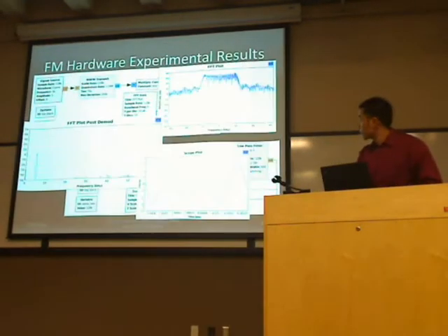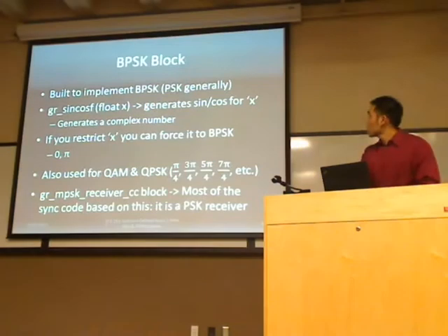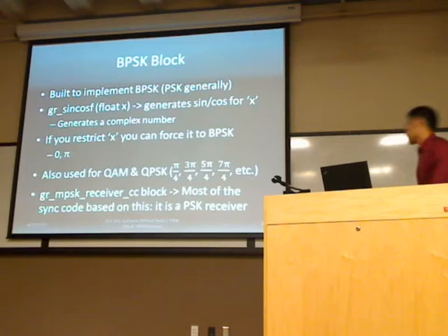And then we implemented it in hardware. We got a very similar result, a very smooth sine wave, and we saw a little less power on the FFT, as you can see, and there's some noise which we think is probably quantization error. And Nikhil will talk about BPSK.